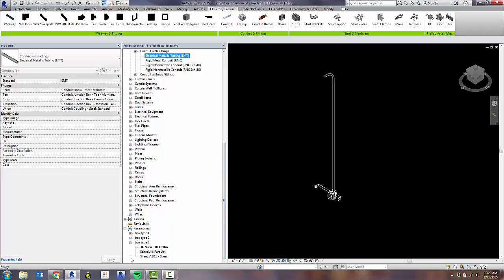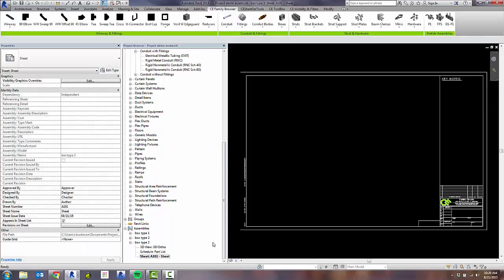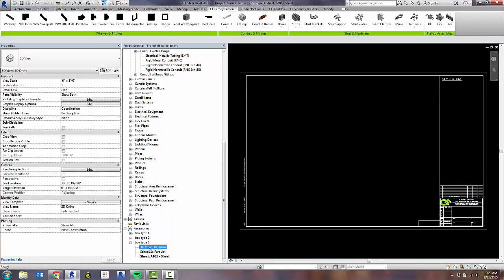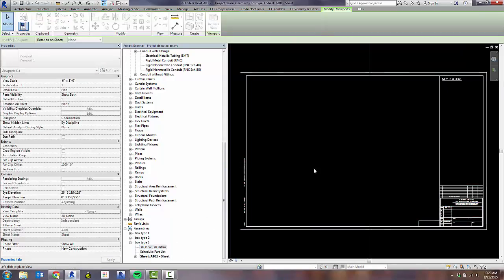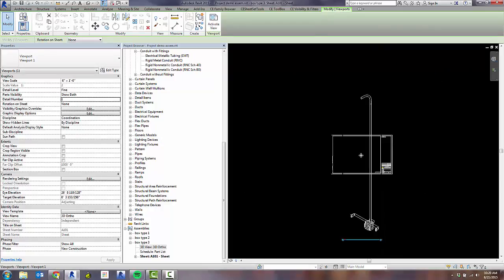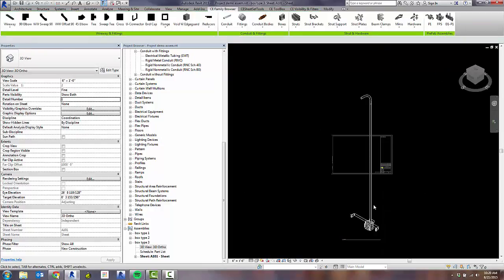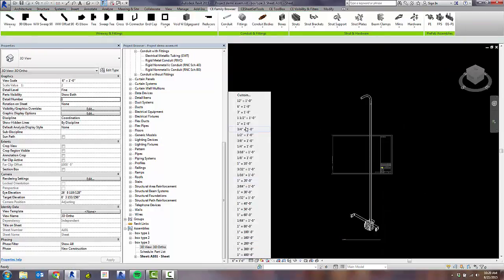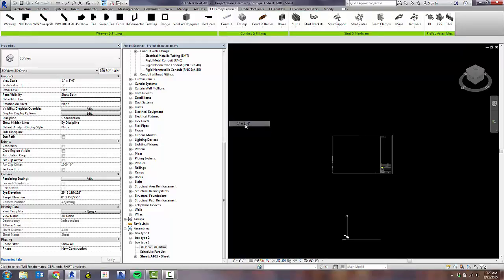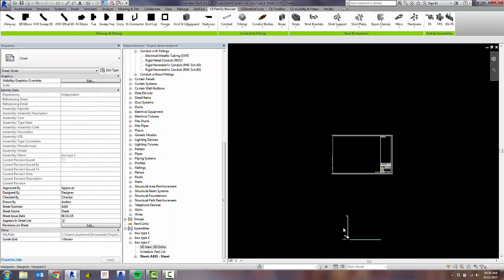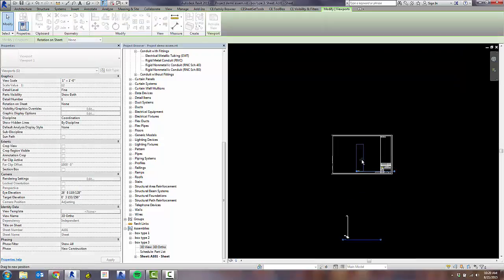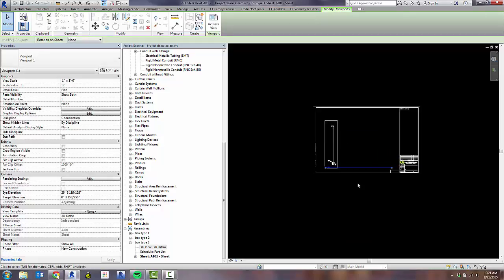Since it already made the sheet, we'll take our ortho design there, and yeah, we're going to have to shrink that considerably. Let's set that to 1 inch. How to do it there. Deactivate your view. Place that on the sheet however you want.